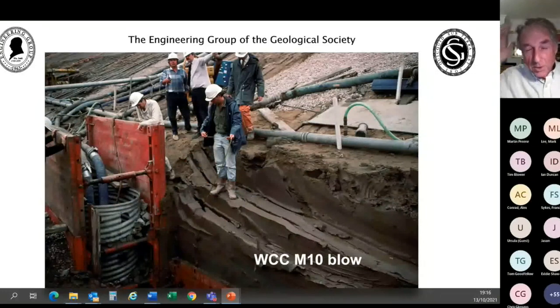So everything was going just about okay. We knew that the pore water pressures in the glacial lake deposits were just about low enough. And then for some reason, it was decided that another half metre or possibly only a quarter metre of ground would be taken off. And that led to just a little tiny spring in the base of the excavation, which over the course of about 24 hours became an absolute flood.